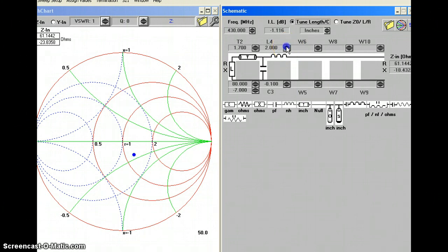So we can come in here and increase this inductance, and we can increase this capacitance. Let's review what we now have. We have an antenna that sits right here. We have a transmission line that's electrically 1.7 inches. We have a parallel capacitance and a series inductance, and that generates 50 ohms. How neat is this? We have taken our antenna, which presents 80 ohms in J7, and we have transformed it through a piece of transmission line and these circuit elements into essentially 50 ohms.